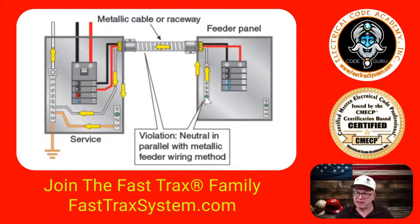This is prohibited. Not only does it create objectionable currents, meaning, as we talked about earlier, here you see if there is any neutral current traveling back to the source, it's going to travel back on the neutral. But some is also going to be traveling back on the metal parts. Now, it's all proportional to the impedance of that path. So obviously, more current's going to travel on the white conductor than the metal enclosure. But when it comes to touch potential, if you have a poor connection for that neutral, then more current's going to travel on the metal parts, and it creates that touch potential. And we're not supposed to be intentionally putting current on the metal parts.